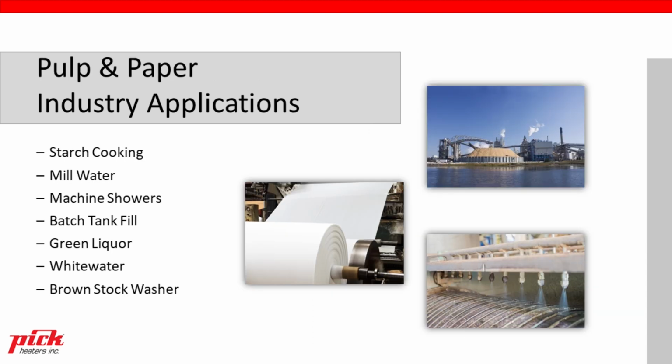Next, another market that's quite common for steam injection heaters is the pulp and paper industry. They do a lot of starch cooking. I think I mentioned earlier for coating paper that steam injection cooking is very rapid and very accurate. They also do a lot of mill water heating, where hot water is used throughout the mill. There are also machine showers, felt showers, Fourdrinier showers, and accurate temperature control is one of the reasons why paper mills often choose a steam injection heater for those types of showers.